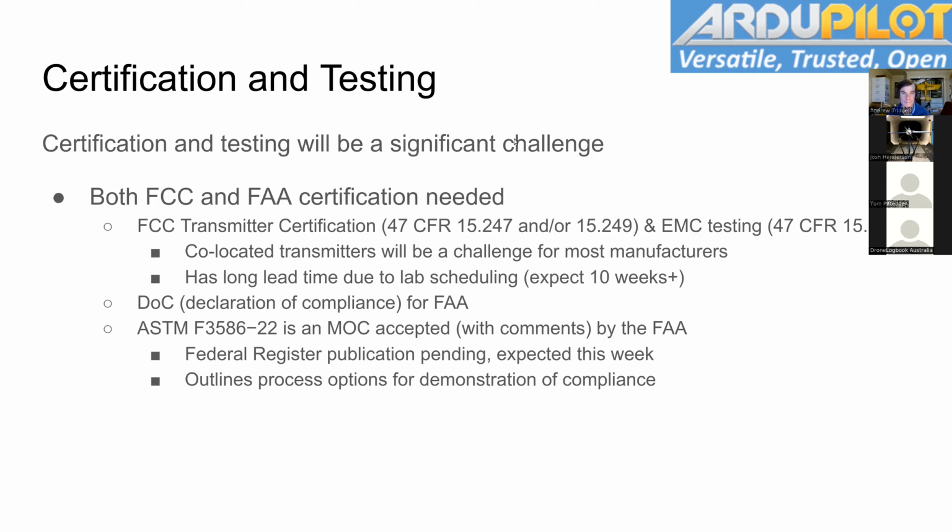So you look up the FCC ID on either the FCC's website or on fcc.io, which is a private service that scrapes the FCC databases. You can look at the test report documents and the transmitter grant, and you can see if it's a full modular or if it's a limited modular.